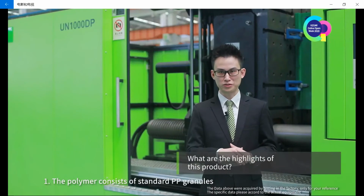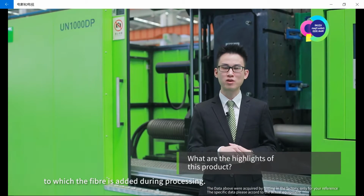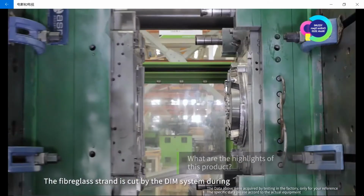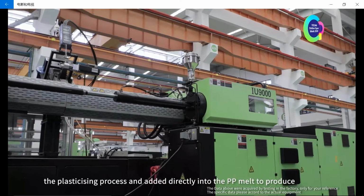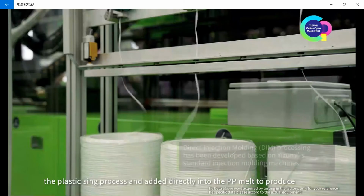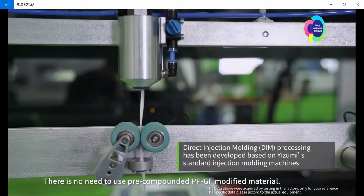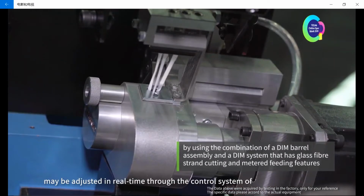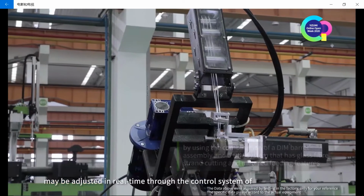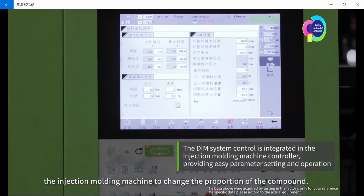The polymer consists of standard PP granules to which the fiber is added during processing. The fiberglass strand is cut by the DIM system during the plasticizing process and added directly into the PP melt to produce fiberglass reinforced product. There is no need to use pre-compounded PP glass fiber modified material. During the production process, the glass fiber percentage may be adjusted in real time through the control system of the injection molding machine to change the proportions of the compound.